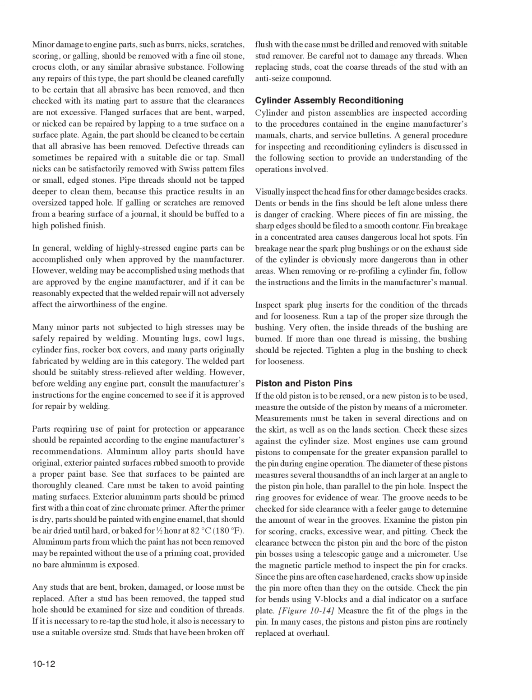for repair by welding. Parts requiring use of paint for protection or appearance should be repainted according to the engine manufacturer's recommendations. Aluminum alloy parts should have original, exterior painted surfaces rubbed smooth to provide a proper paint base. See that surfaces to be painted are thoroughly cleaned.